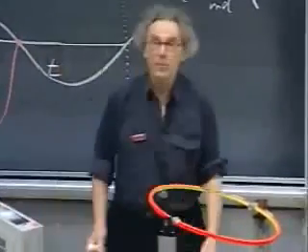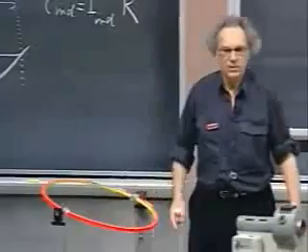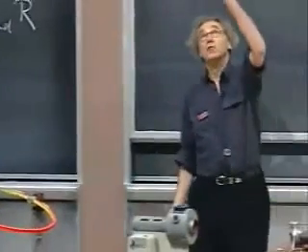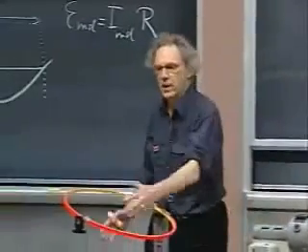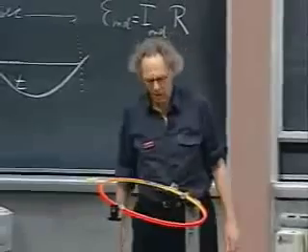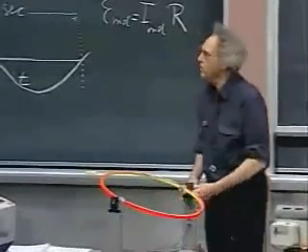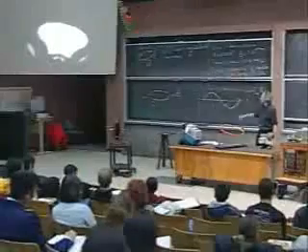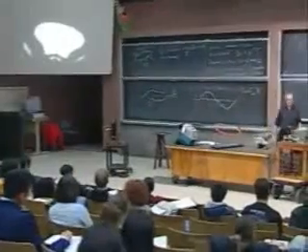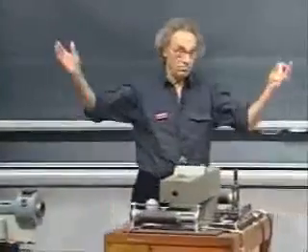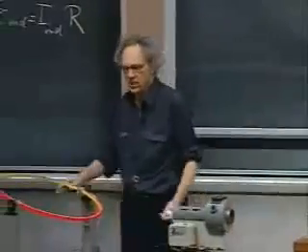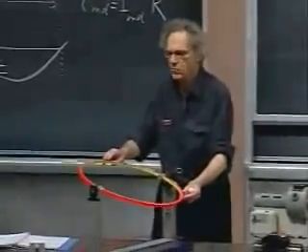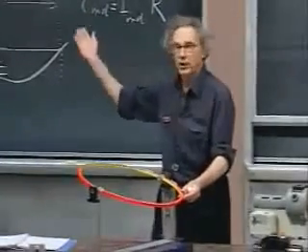We don't have that problem at all, because the magnetic field here on Earth in Boston doesn't come straight from heaven down, but it comes rather steep. So there's never any problem here. I don't have to worry about that. So here is that loop, 42 windings. The scale there is in microamperes. So if you want to, you can calculate what the resistance of the loop is when I rotate, but that's really not my objective. I want you to see that when I rotate it, you get an alternating current.